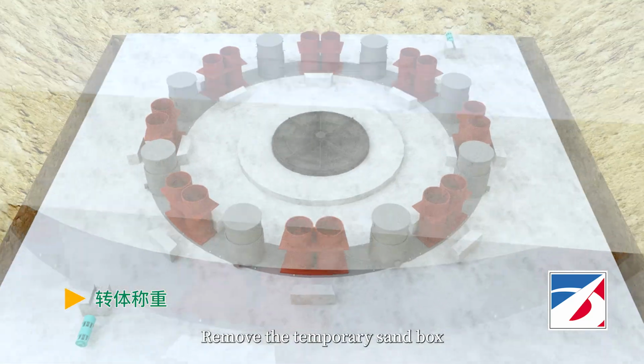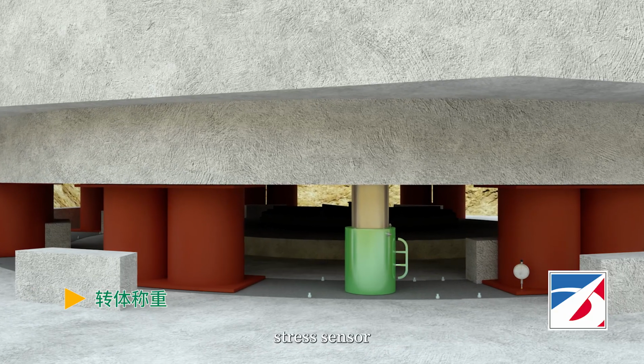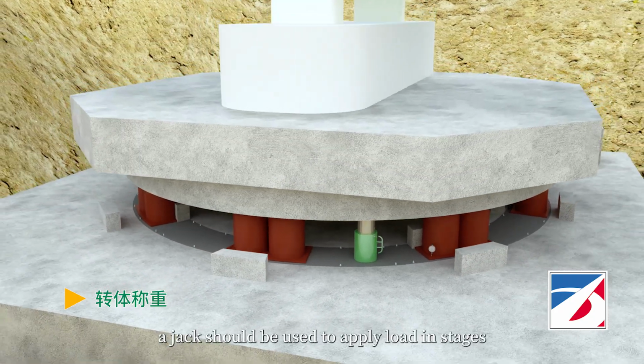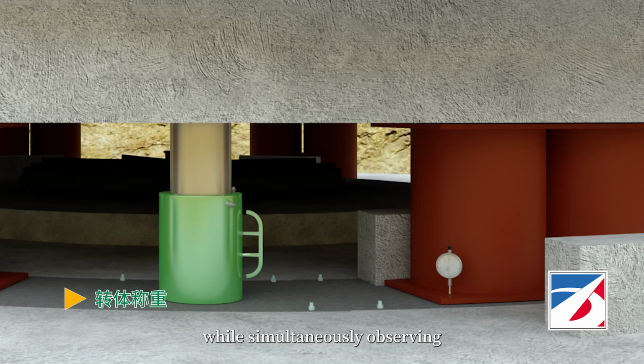Remove the temporary sandbox. According to the landing condition of the support feet, arrange the weighing jack, stress sensor, and digital dial gauge. During the weighing process, a jack should be used to apply load in stages, while simultaneously observing the displacement of the dial gauge.